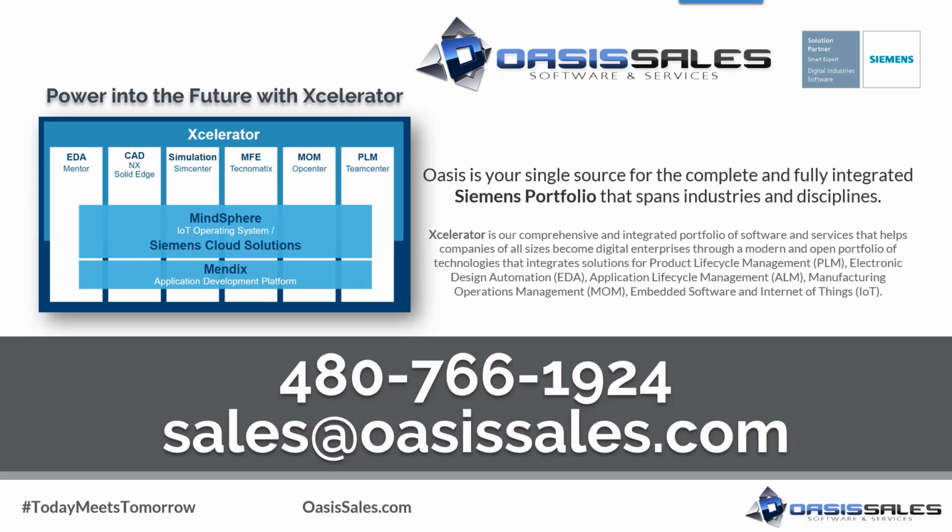One of the first questions we have after going through today's webinar was, could we use the territories approach for the whole PCB? Yes, potentially you could. Absolutely, there's nothing stopping you from doing that. However, depending on the complexity of the board, you are going to have a lot of detail, and realistically, I think you're probably going to run out of mesh. And I don't know how much more accuracy it's going to add. So it's really about balancing simulation time with simulation accuracy, and I think that's probably a bit overboard.